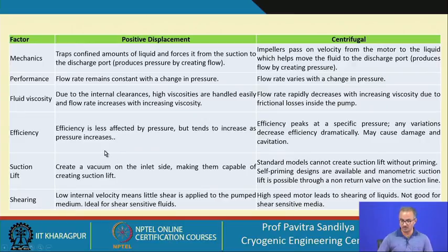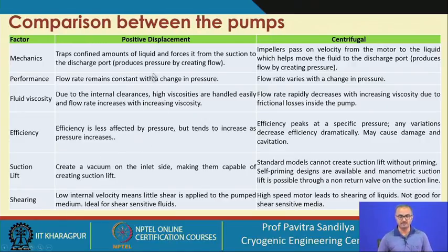And here is a small comparison between the different types of pumps. These are positive displacement pumps and centrifugal pumps, and their differences are on various bases, like their mechanisms, their performance, the fluid viscosity they can handle, the efficiency, the suction lift and the shearing. As we learned, positive displacement pumps trap a certain amount of liquid and push it, whereas in centrifugal pumps we impart energy to the liquid by centrifugal force, and then we convert that energy to pressure head.